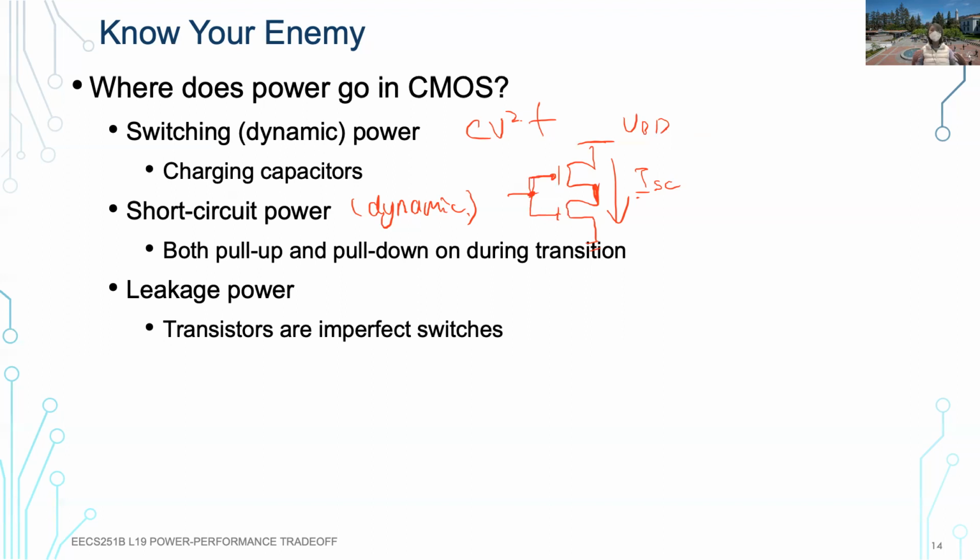With voltage scaling, the threshold doesn't scale, so it's very hard to turn on both, because this requires both to be on, right? So this is a side benefit of scaling not working. We cannot pull down the threshold voltage anymore. So it's a side benefit that we basically cannot turn on both of them. So people still talk about short circuit power, and typically in the report they lump it together with the dynamic power, but it's less important, especially with advanced technology.